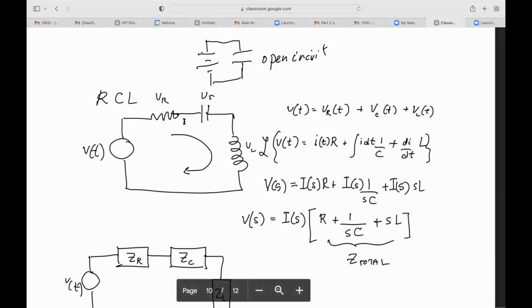Now, the importance of knowing the impedance of all these components is that you can combine all of these in different combinations, just like so, right? And right away, you can express this circuit as a differential equation. But it's messy to deal with differential equations, especially when there is also an integral like that, right?